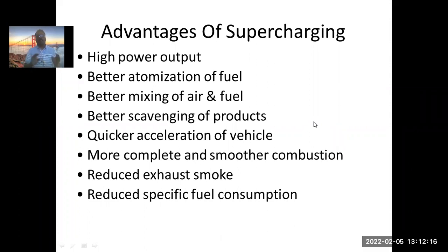When compared to a normal engine, we are saying that scavenging is better. How is it better? See, what happens to the initial pressure inside the combustion chamber? Initial pressure has increased. Why? The charge we have densified. That means initial pressure itself has increased. What happens to the final pressure? Final pressure also increases.